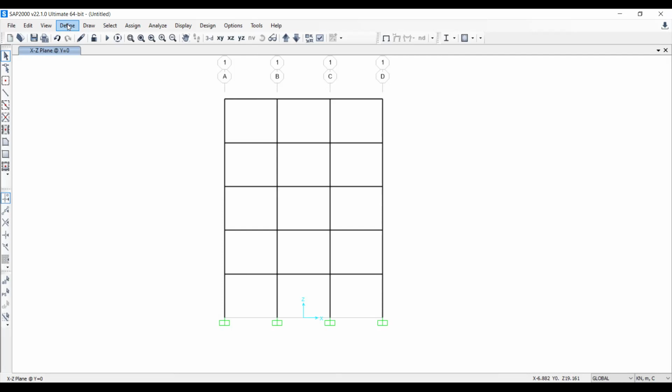The dead load could be the self weight of the building itself. It could be the partitions. By partitions I mean walls, which could be masonry walls, brick walls, cement walls, and also the tiles, the paint, the plastering. All this we can call partitions, like a superimposed dead load.